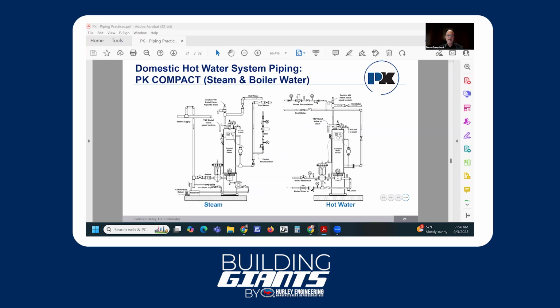And I want to just add to what Daryl's saying about you can still control on a gasketed plate. Yeah, but they exchange heat so rapidly, it's difficult to precisely control it. You can lose control pretty quick, is what Daryl's pointing out. The other thing is the shell and tube, they're easier to clean. And these devices with the circulator pump prevent the formation of scale better than a gasketed plate. Would you like to add anything to that, Daryl?